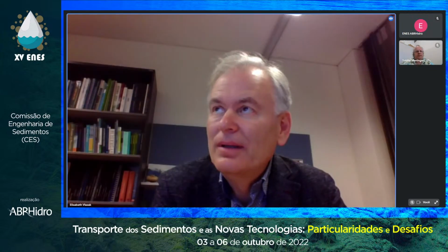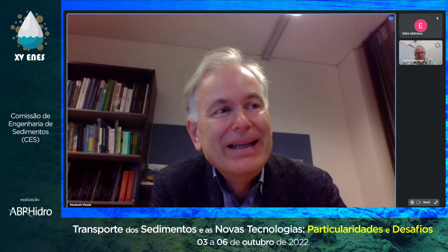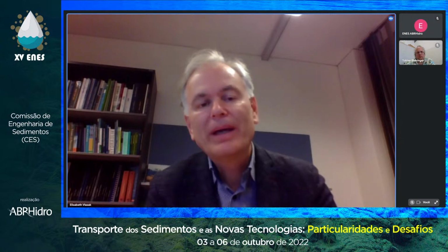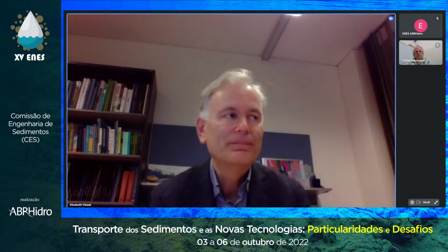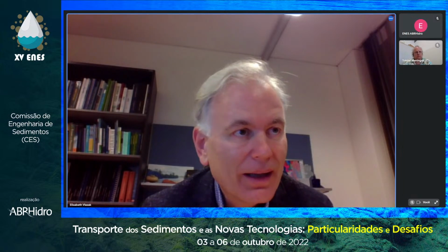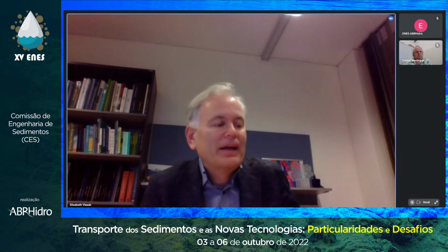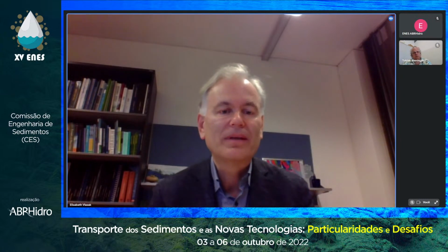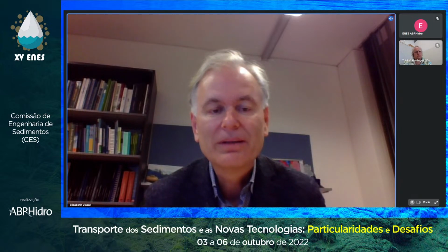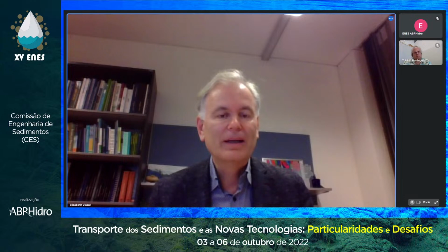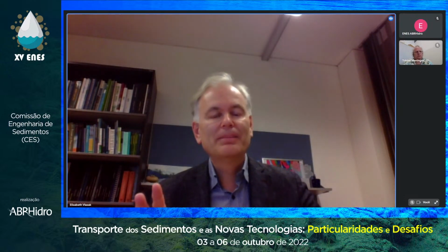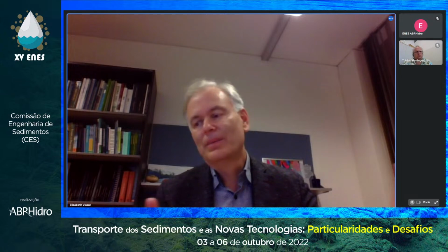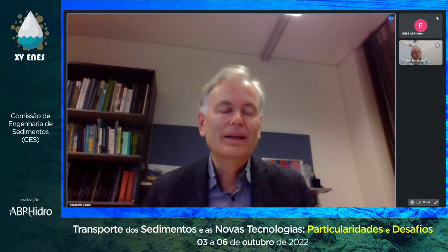To my point of view, it is. You cannot do one-to-one the same, I guess, but the idea could be the same. Because I know that there's a lot of data by ANA available. So in a way, what you would start with is to try to build up a sediment budget. Even if it's not perfect, it can never be perfect, but you would want to start with a sediment budget, and then a change of the riverbed or the reservoir bathymetry, and then you start combining the sediment budget and comparing it with the changes of the morphology, and so on.